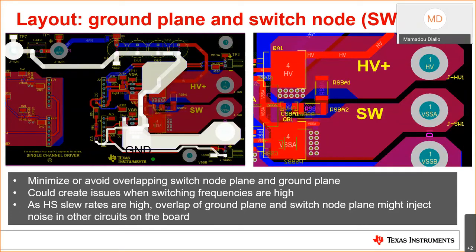So with high slew rates on the inputs and on the switch node, the overlap of the ground plane and switch node might also inject noise into other circuits on the board. So it's really critical to have an optimized layout. We, as a team here, are open to help customers design their power stages. We help them optimize their layout and make sure that it is optimized to use the gate driver in a specific condition.